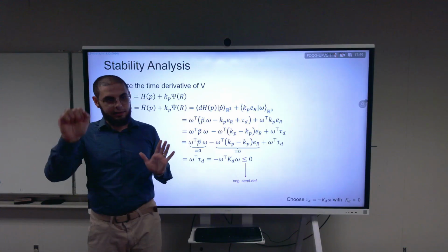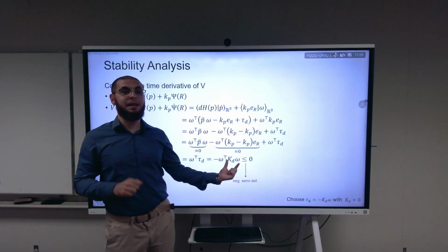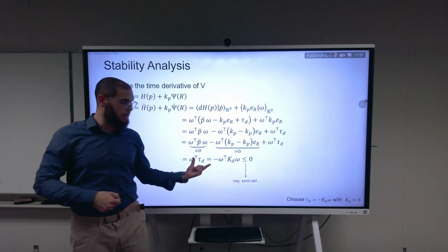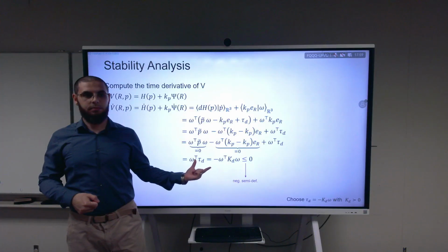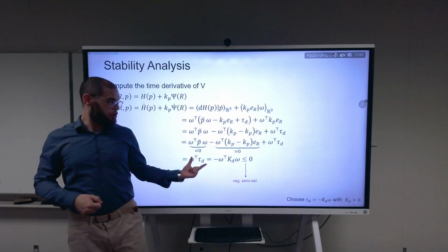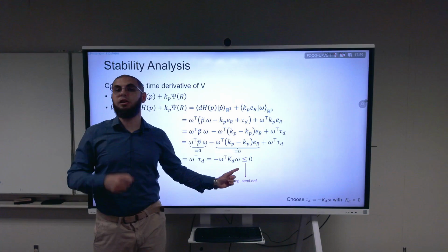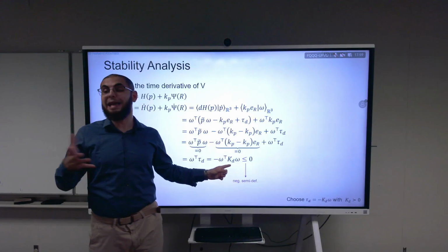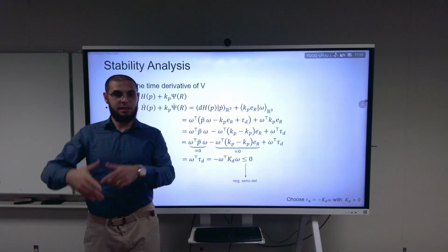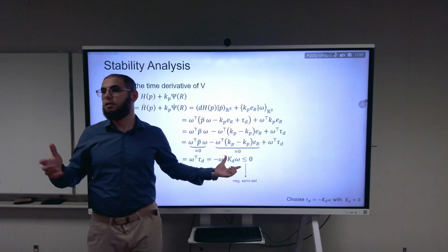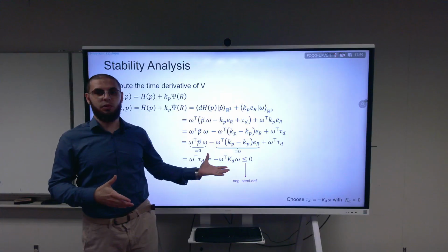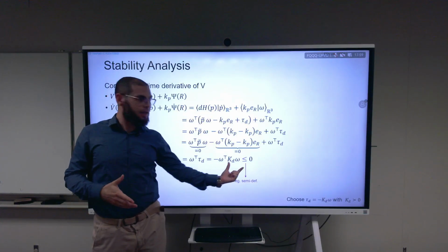Okay? And I'll tell you even something better. I can even make it a time-varying function of omega, and still this will be the same. Okay? So I can make the derivative term here a time-varying function. So in case you have an application where you want, for example, kd to be time-varying, this is usually what people do, for example, in haptics. You actually want the damping to change with time. Nothing in the Lyapunov analysis will change. Because it's still negative definite.